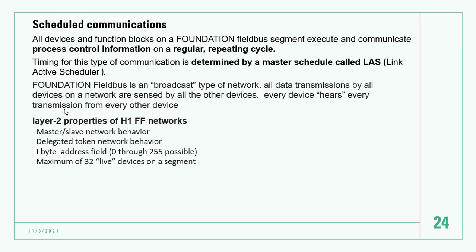Foundation Fieldbus is a broadcast type of network. All the data transmitted by any device on the network is sent to all the other devices. Every device hears every transmission from every other device.